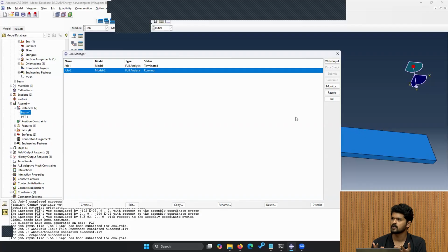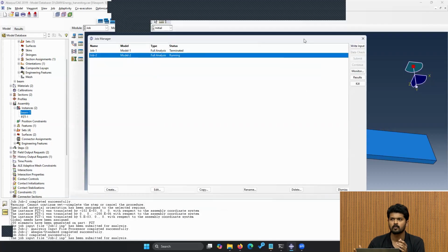But when you are solving a problem, you might need to automate your code. For example, you can use MATLAB and its optimization toolbox. But how is that toolbox going to access your software backend, not through the graphical user interface, so that you can run your optimization problem or parametric studies? There are different ways to do it. Abaqus itself has a Python interpreter, so you can generate a Python script. One other way that industries use a lot is using the input file.